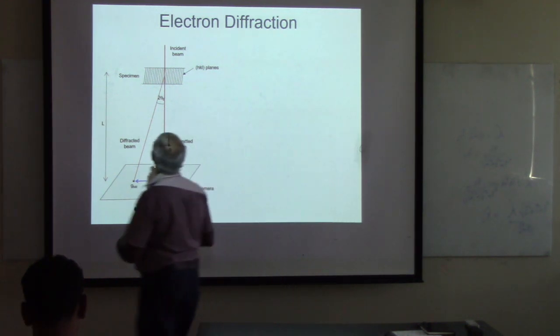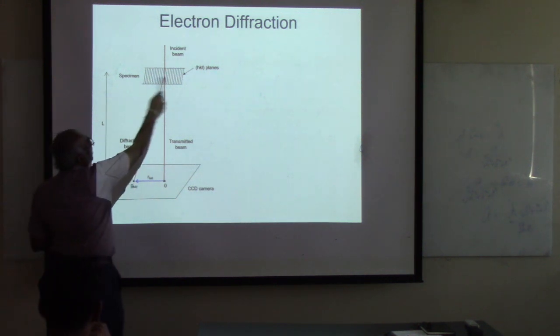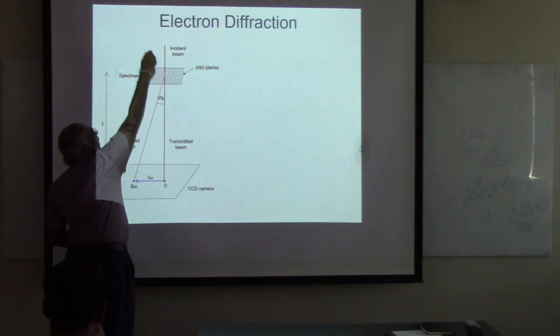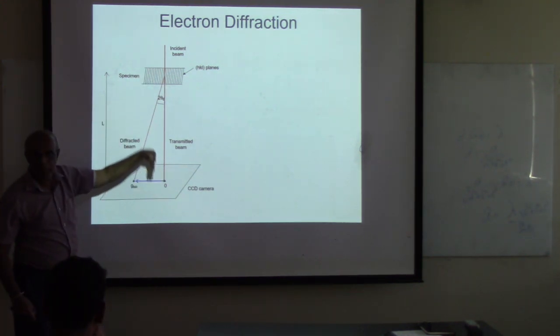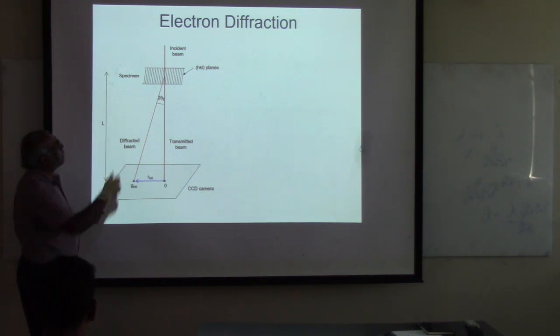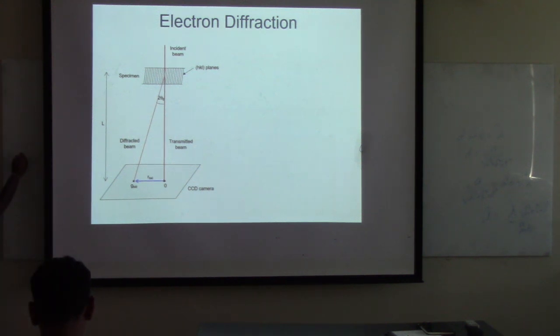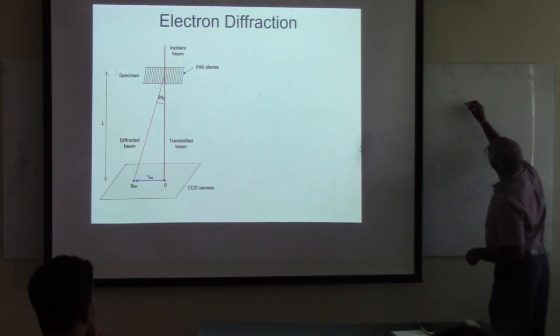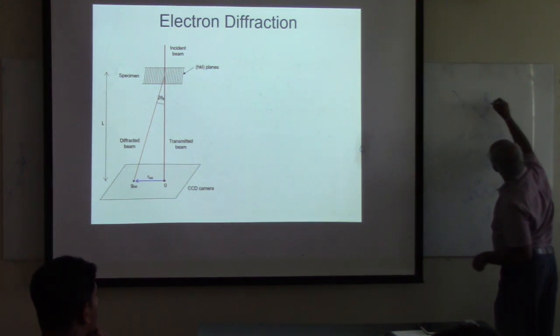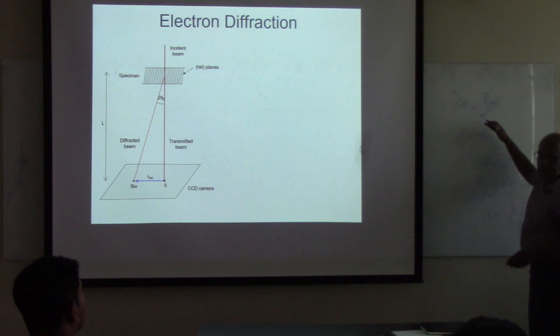Typically in TEM, we have samples, suppose your crystal planes are like that, and you have an electron beam which has to pass through, right? That's why we have to make a really thin sample. If the electron beam comes like this, this is the angle. Please remember, you always measure the angle from the crystal, so it will diffract like this. This is theta. Then what is the diffracted angle? 2 theta, right? Please remember, the deviation from the original direction is always 2 times theta.